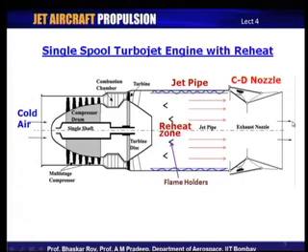So, it is necessary that you take care of the pressure available at the exit face of the nozzle a priori, well before, in your design of this jet engine, because when you are raising the temperature, it is necessary that it already has a high pressure available with it. Only then you can deploy a CD nozzle to create a high velocity jet. Only high pressure or only high temperature would not do.